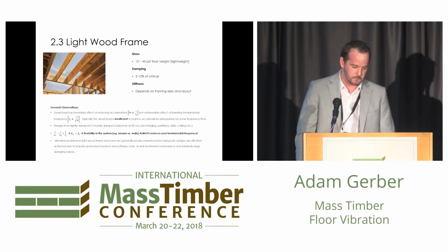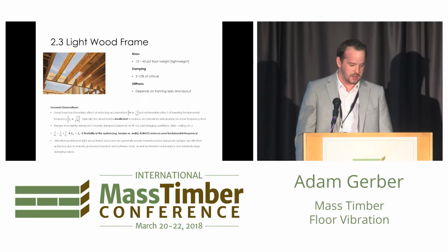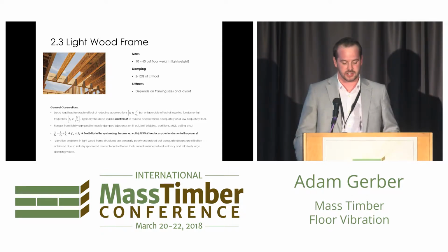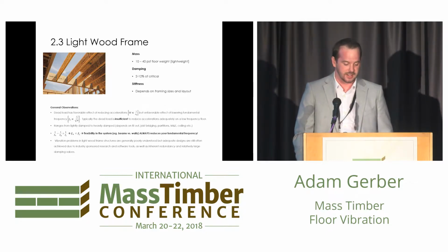Light wood frame, 10 to 40 pounds a square foot floor weight, so it's definitely a lightweight structure. Damping can be sort of 2 to 12%. And the stiffness, again, it depends on the framing sizes and the layout.